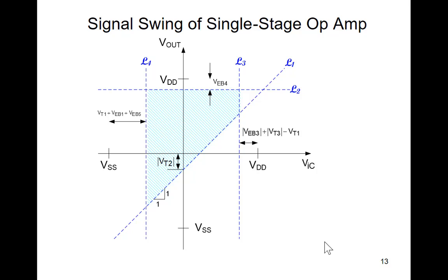The op amps you worked with in 230 or in the lab this time, can you take your inputs clear down to VSS? No, you go down too low and it quits working. Can you take your inputs clear up to VDD? No, it quits working if you take them too high as well. Something like this happens on the inside. You can with the LMC 660. Some op amps are designed, and we'll talk about how to design op amps, to go rail to rail, but this was not designed to go rail to rail. Some are designed to go to one rail and not the other rail.